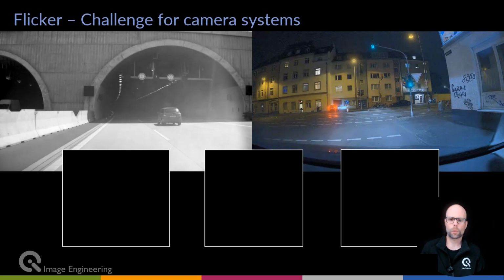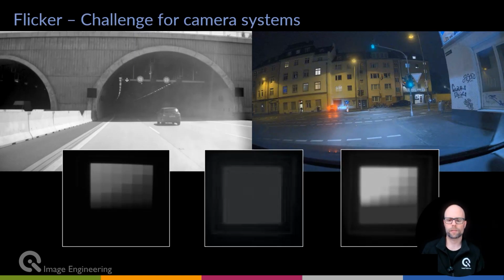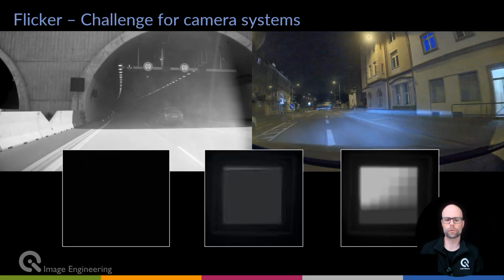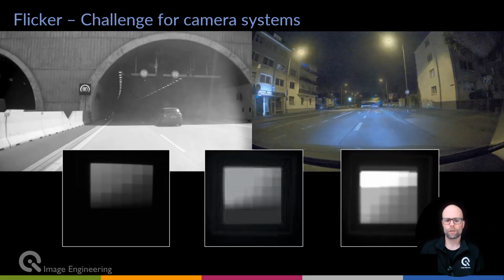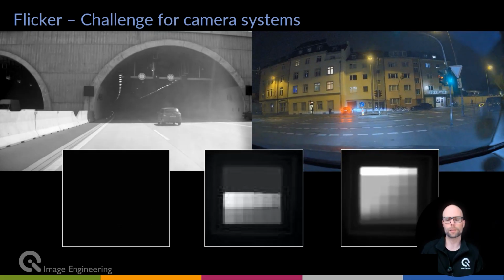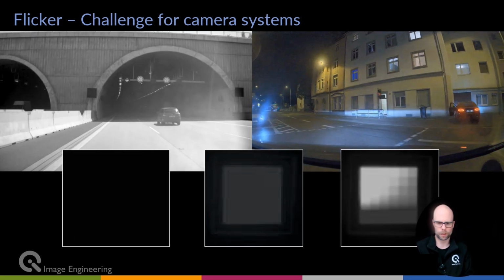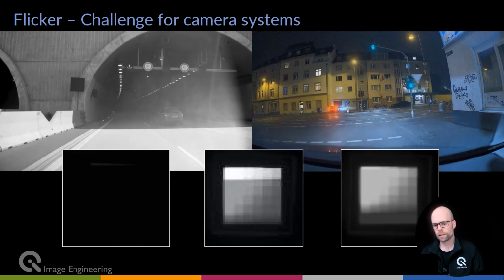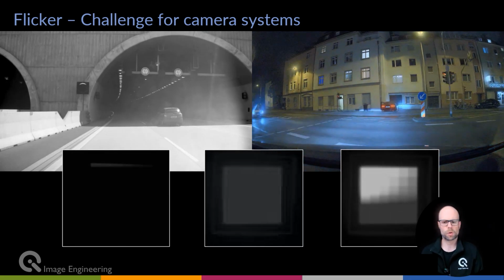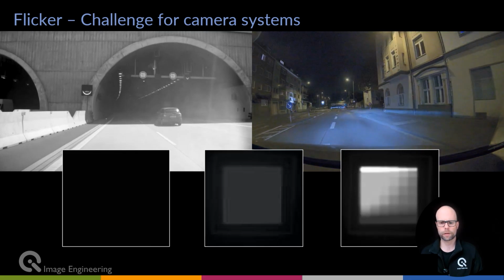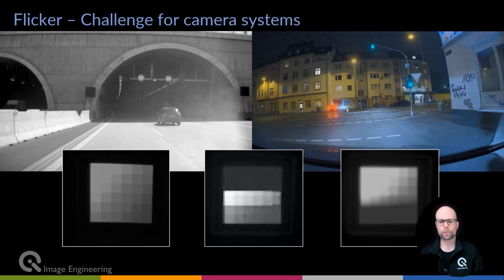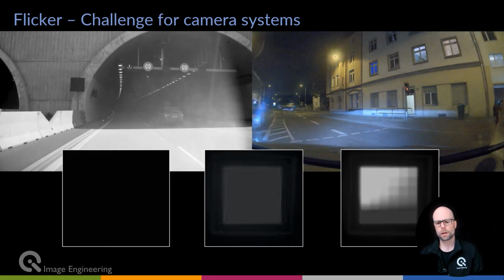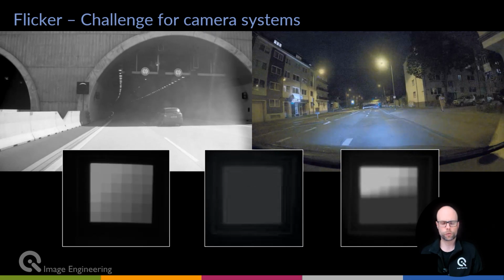So when we say flicker, these are the effects that I typically talk about. For example, you see on the left there's a road sign, 80 kilometers per hour. For a couple of frames, it's invisible to the camera because the camera has a problem with the PWM that this road sign has. Also, in the scene in the top right, there is something of an annoyance because these road lights also use PWM, so that causes a general flickering effect on the entire image that you capture. That's at least an annoyance, if not really a disturbance for the detection algorithm.